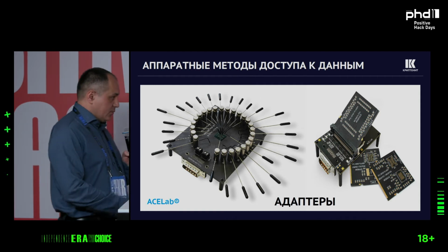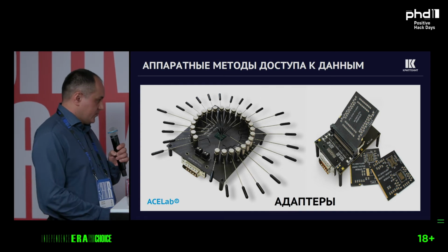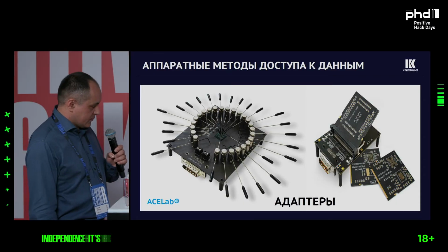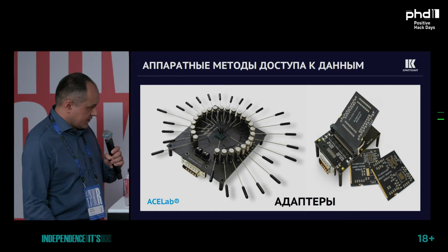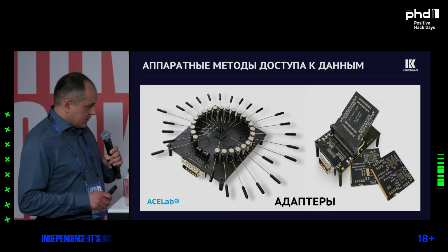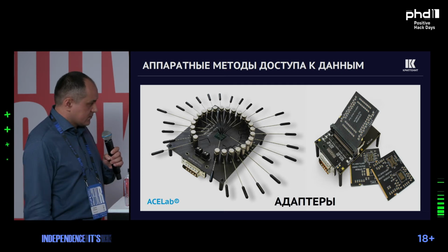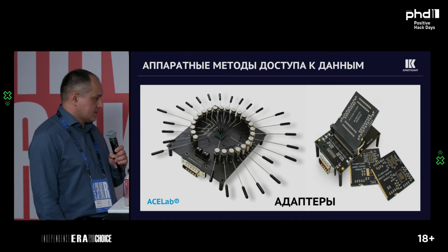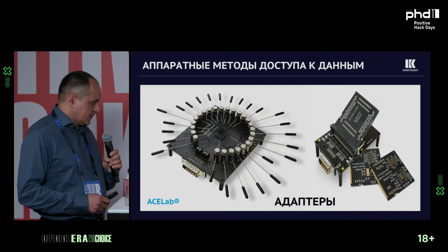And it's important that PC 3000 Flash has a spider board. It helps you use the needles to connect to the memory chip, define the core voltage, and automatically define the interface. So the program itself defines which interface is being used. In most of the cases it works.